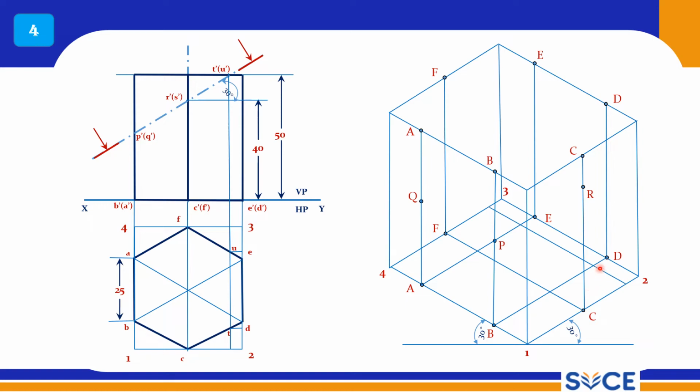From this intersecting point you can measure 50 mm and mark point T. Otherwise you can measure directly here and mark T. That is also correct. Here also you can draw that small rectangle and mark U. Otherwise you can get each and every point from the base, which is also good practice. So this is U, and this is your point S.